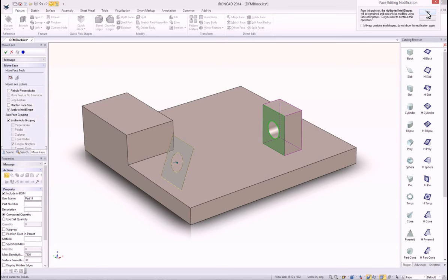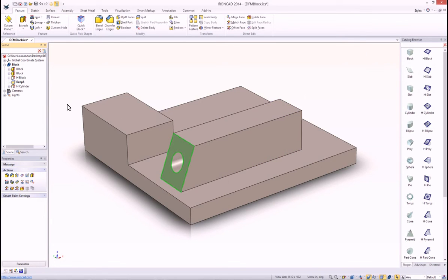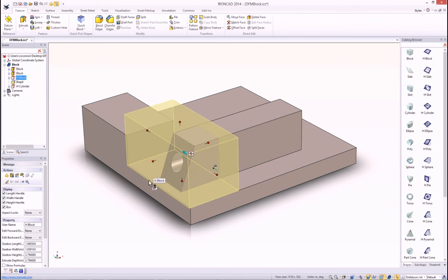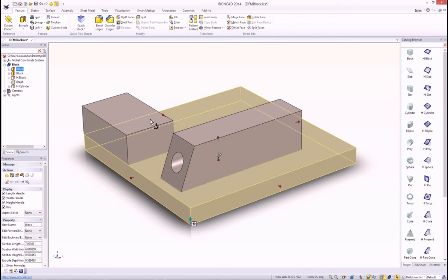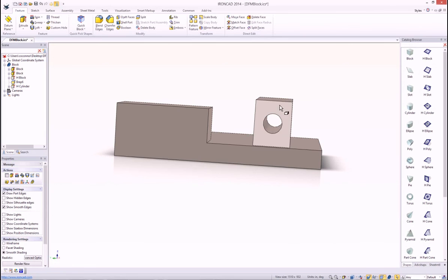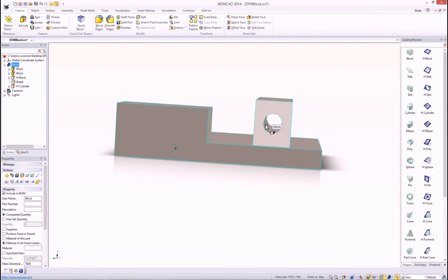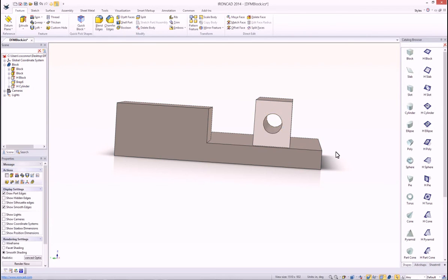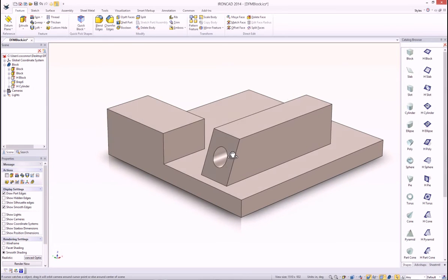So we'll go ahead and apply that change, and you'll see again it actually combined that feature into a direct editing feature, what we call a brep, and inserted it again into the structure where it needs to be in order to give a predictable result. But it leaves all our other features as regular feature definition shapes out here that can be modified, and maintains our definition of other objects, like our hole, for example, which is still set to extrude through the face in the location that it was initially defined.